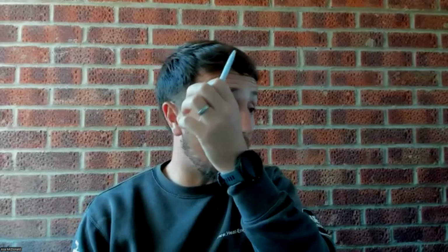I think that's one part you might need to make a note of if you can't remember it from the survey itself or the pictures you've taken. You might need a list of materials, and then as I referenced and showed in the Heat Engineer software, you can build that U value manually, or we've got the materials from the heating design guide with preset U values that you could utilize.